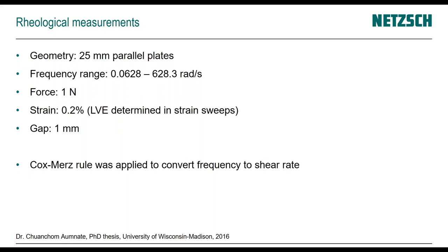Now I want to talk about the compatibility, and the rheological measurements we did are pretty straightforward for a lot of plastics materials. We used a standard 25mm plate diameter, varied the frequency, had a low force, a strain in the linear viscoelastic region, and a gap of 1 millimeter. And all the results you see are shown as a function of shear rate, because we could use the Cox-Merz rule to convert frequency to shear rate.